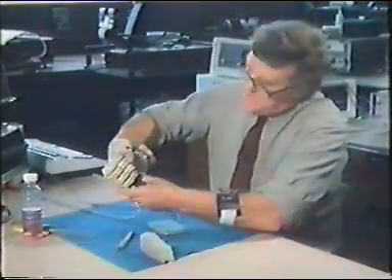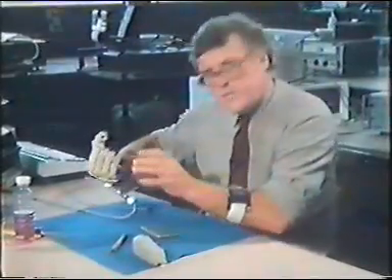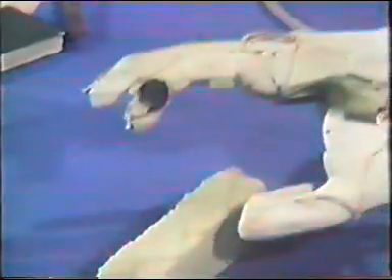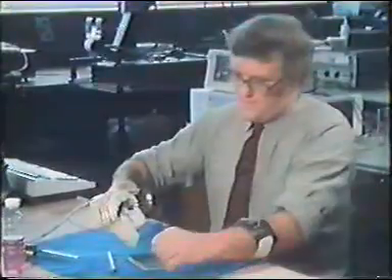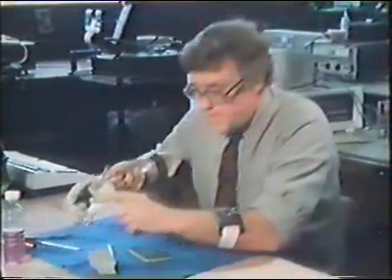There's an even more interesting sensor on this, and that's here in the thumb, and all it is, is a microphone underneath this piece of Velcro. And when I want to pinch something in between the fingers, I can pick up this piece of sponge like that, and as I pull this piece of sponge out, or attempt to, the sound is transmitted from this sensor here into the computer. When it hears the sound, it automatically tenses up the hand to stop me from withdrawing this piece of sponge. In other words, it's a complete feedback mechanism. No signal from my hand is affecting it. And I can simply open the fingers and let it drop. There's another sensor here on top.